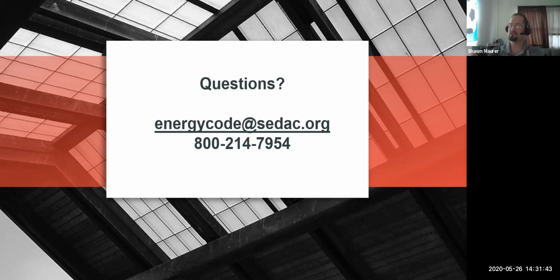We are looking into how much relative exterior insulation you need relative to your cavity insulation to prevent dew point risk. The more cavity insulation you have, the more that exterior sheathing is going to drop in temperature and the greater risk it's going to have. So the more exterior insulation you would want to compensate with. So we're trying to look into that a little bit and come up with some answers for that we'll post.